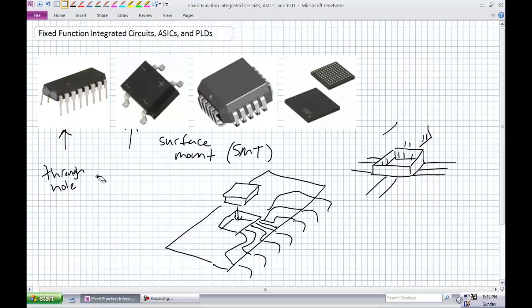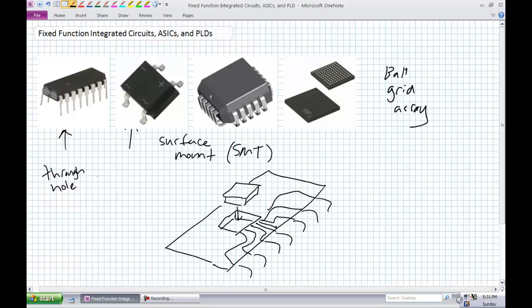Okay, this one on the furthest one on the right, it's what's known as a ball grid array. Okay, just like catching a frog and trying to see what the sex is, you flip it over, there's a bunch of balls on it. The reason why is, think about this, you're limited to the perimeter for the number of leads. As these things get incredibly more and more complex, you might not have enough area there. So why not make the whole area, the bottom of this thing, have all the connections? And again, this obviously requires a special